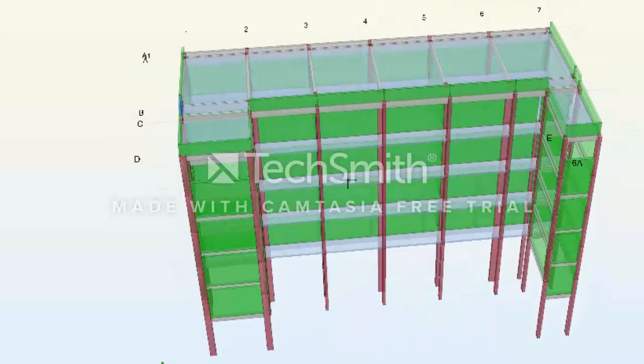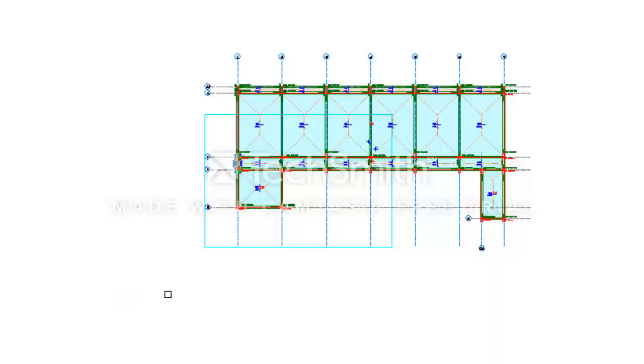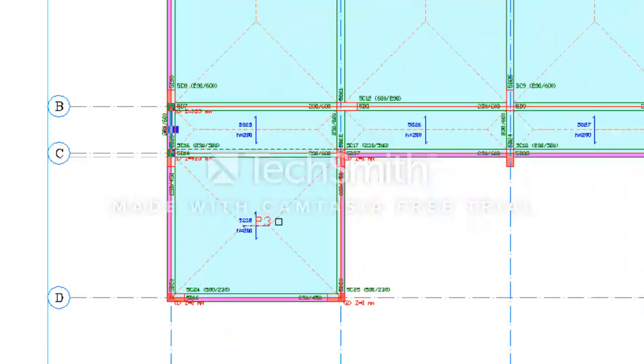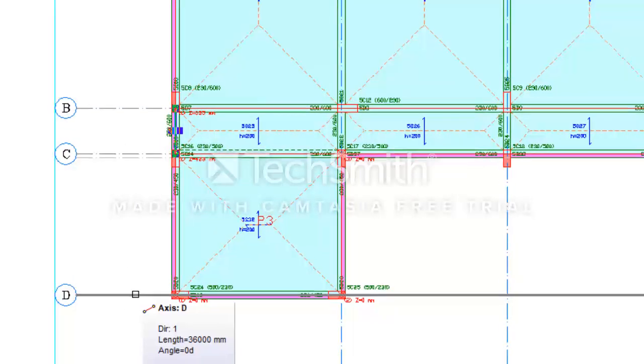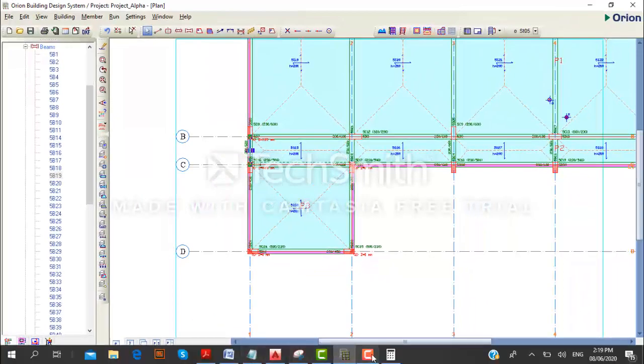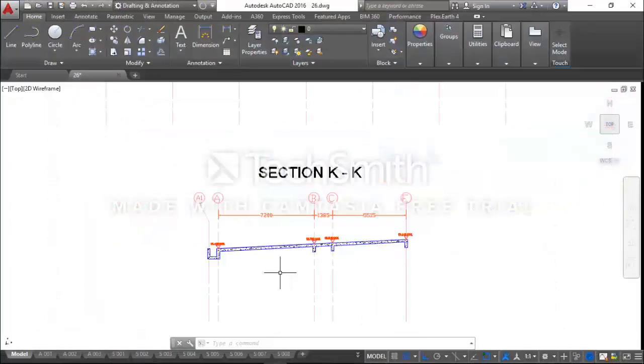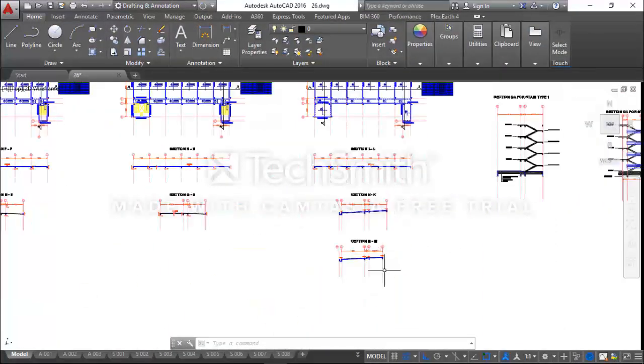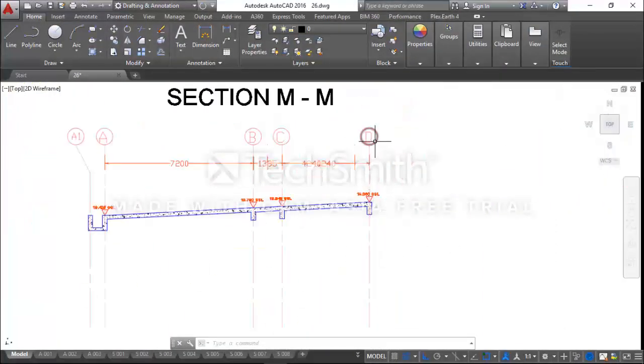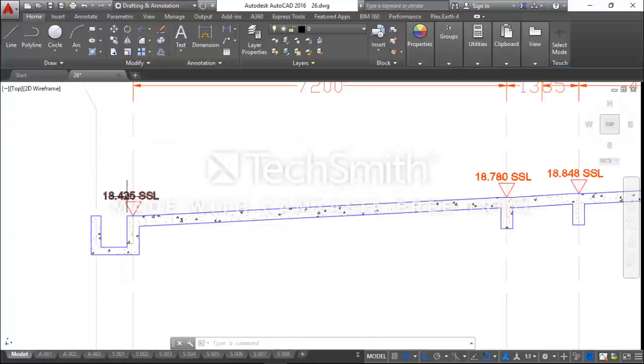Now we have to deal with plane definition 3 and 4. I'll deal with plane definition 3 first. Our Z value for C, we say is 423. Our Z value for D, we'll go to our drawing and determine. This is line E, this is line D. So our Z value for D will be the elevation here minus this elevation.